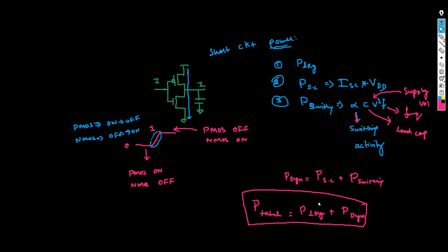When you are working on a mobile chip, your static power is important. It could be 100 milliwatt or 120 milliwatt, something like that. When you are working on a CPU, mainly ARM core CPUs, quad core or octa core, you may have 100 milliwatt or 60 milliwatt targets per core. That is your leakage power target, and then there is dynamic power.